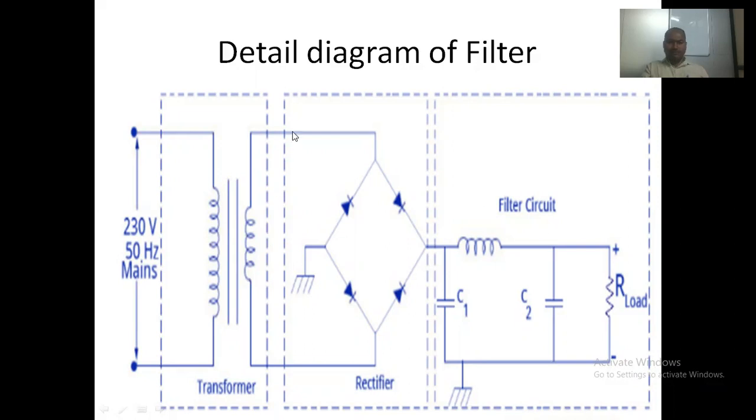So accordingly there are two half cycles with respect to AC, the positive half cycle and the negative half cycle, right? During the first positive half cycle, positive is coming across here and negative is coming across here. There are two diodes, here is one diode, here is one diode. Consider that the first conducting diode is D1. So diode D1 is conducted, and during that time positive voltage is coming across here.